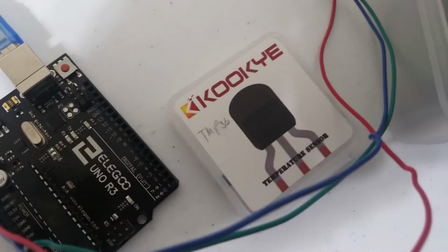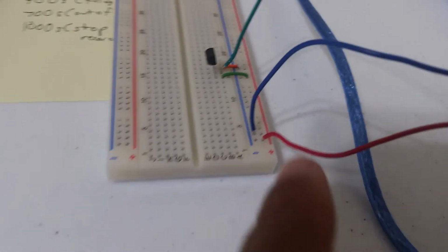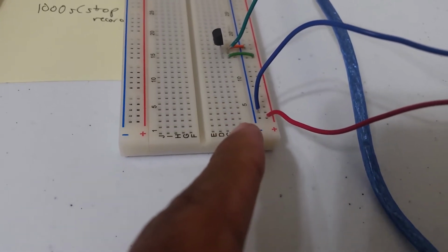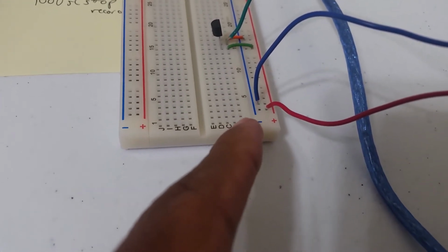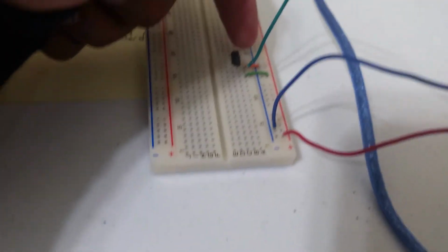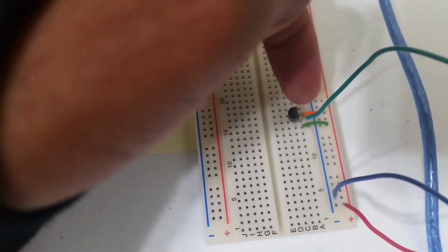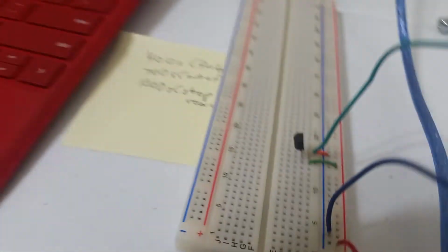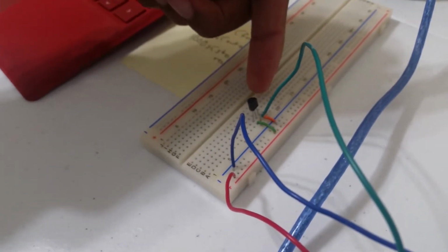And all of these wires are connected over here. Oh, here's the case for the TMP36 sensor. All of these wires are connected to the breadboard, which you can see here. So the red power is connected to the positive rail right here. The blue wire, which was connected to ground on the Arduino board, is connected to the negative rail here. And then we have this orange wire over here, if you can see, connected from the ground, this minus rail, over to the far left of the temperature sensor over here.